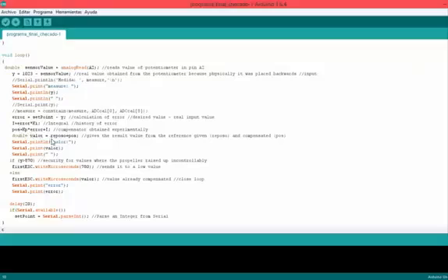And then with this value, valor, we write it to the ESC with these parameters, but we made a security limit: if the motor is beyond 87, we write this limit value to the ESC, and if it's below, we write the value that we calculated.